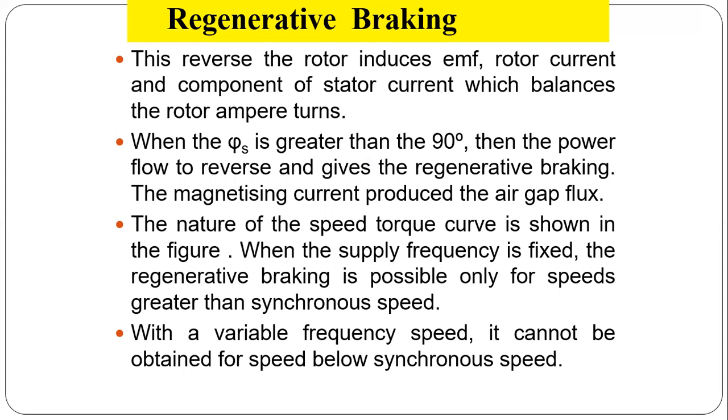This reverses the rotor induced EMF. If the field is reversed, it reverses the rotor induced EMF, also the rotor current and the component of stator current which balances the rotor ampere turns.